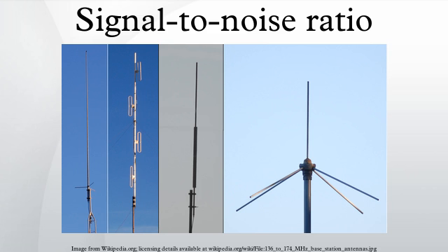broadband noise. When the signal is constant or periodic and the noise is random, it is possible to enhance the SNR by averaging the measurement. In this case, the noise goes down as the square root of the number of averaged samples.